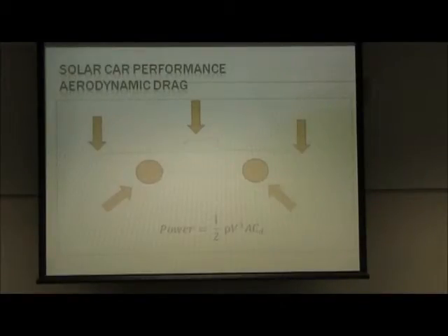Okay, let's talk a little bit about some of the aerodynamic performance. Here's a car, the front edge of a car. What happens when you run the front end of a car into the wind? It has to split the airstream. If you're lucky, what does the airstream do along the surface? Laminar flow. It flows right along with it, which means there's very low resistance. And then at a certain point, about the time your array starts and it gets a little rough, or even if it's smooth after a while, you get separation and turbulence.